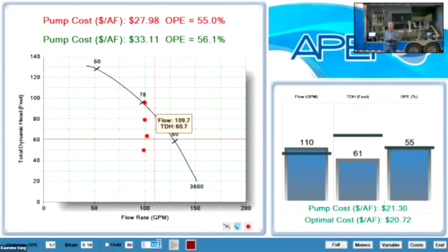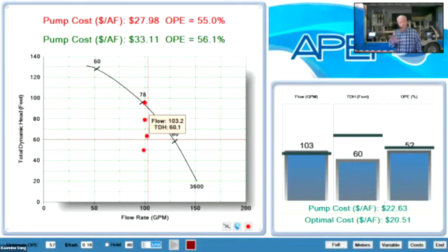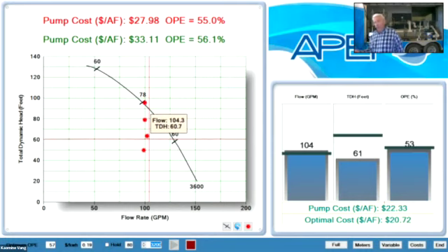And hopefully we're maintaining our 100 gallons a minute or something like that. You get the idea. So the point is, for a variable or fluctuating water table, the pump can speed up and slow down. This is just one example of how a VFD is sometimes being used here, so growers aren't having to pull their pump out every few years and put a new, bigger horsepower in because the water levels keep dropping. You oversize it, hopefully maybe it'll last for 10 years or something after that, and you don't